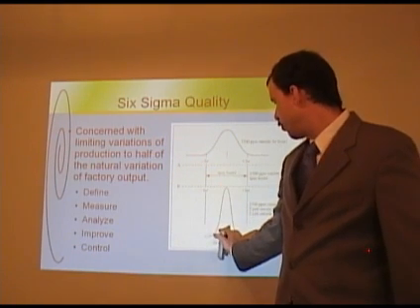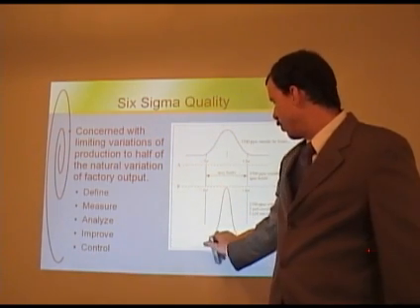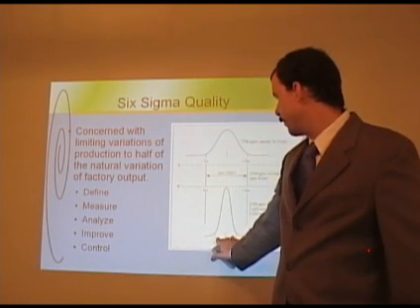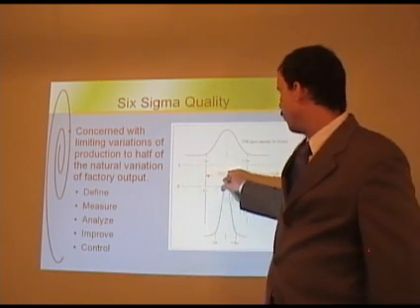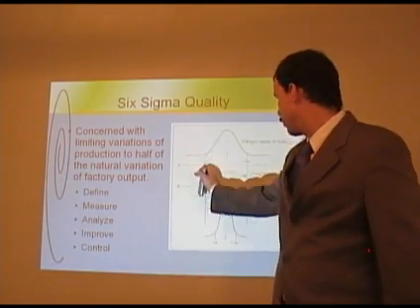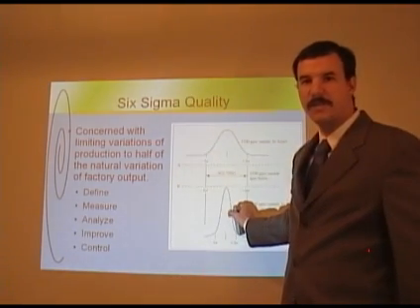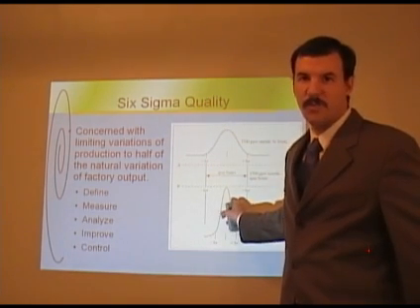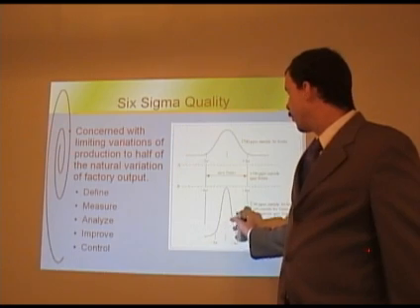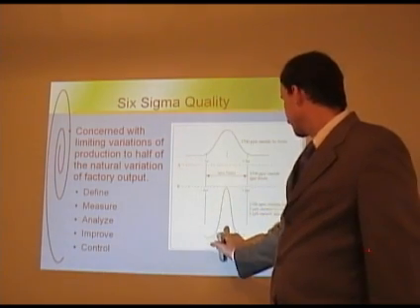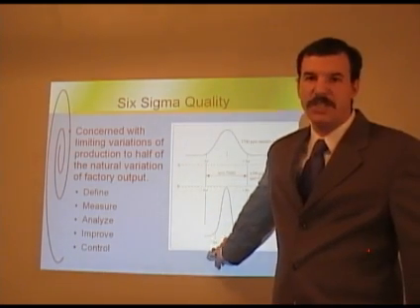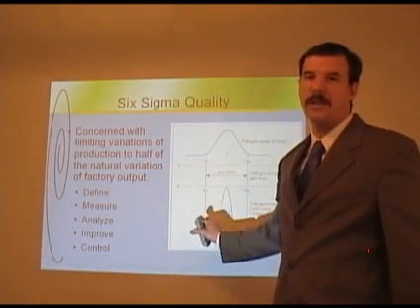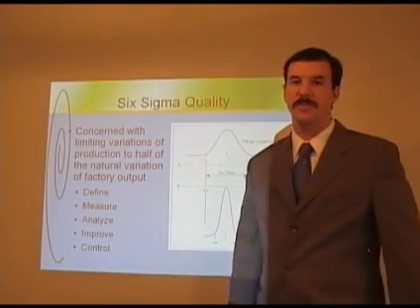Your 3 standard deviations would be well within the spec limits of what you're producing, and what the previous spec limits were set as would then be considered 6 standard deviations from where you are. So what that means is that your variations will be a lot more rare, and you would have a lot more quality built into your production system.